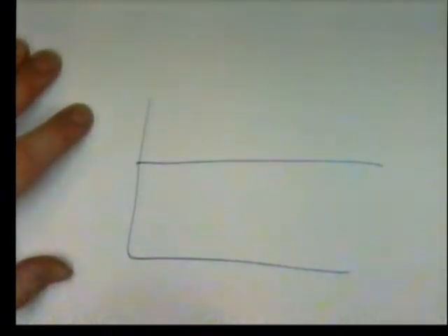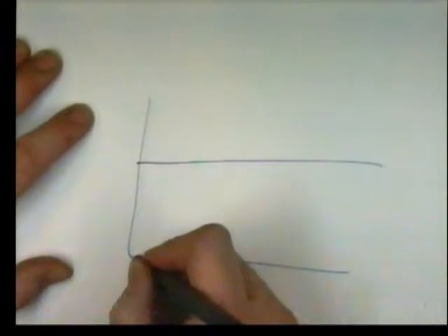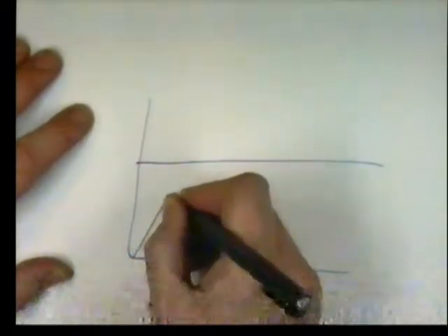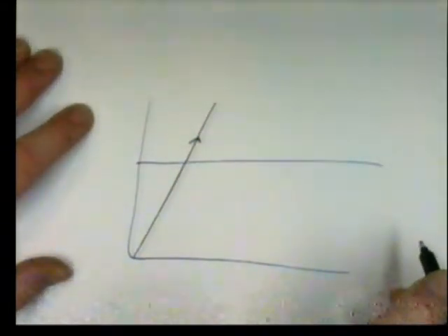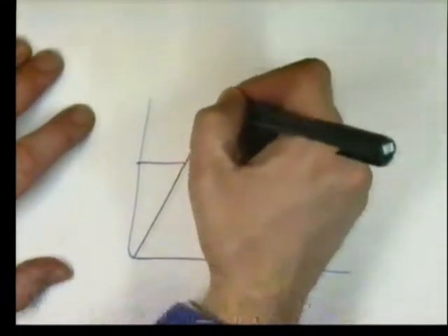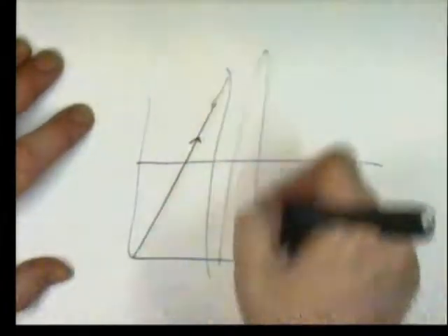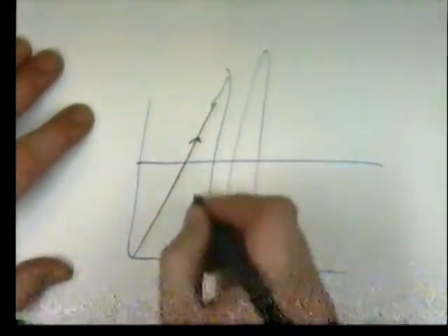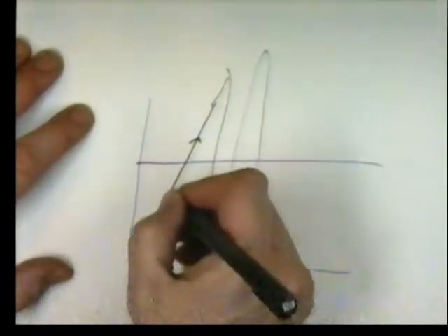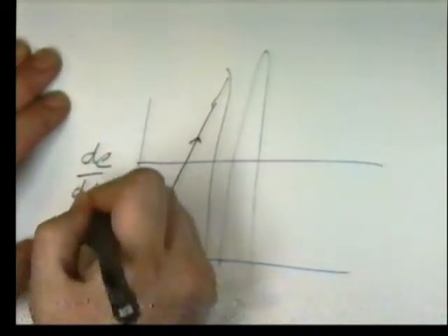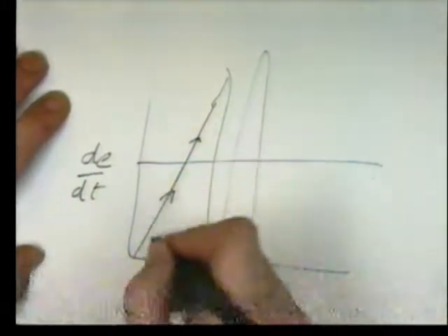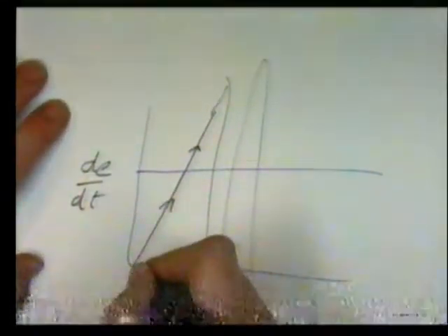What it means is that here's our measured variable. If it is accelerating at too fast a rate through the set point, it's likely to go into this unstable position. What we want to do is that near the set point, if we detect that this rate of change, the dE/dt of the error signal, is too great, we want to slow things down.